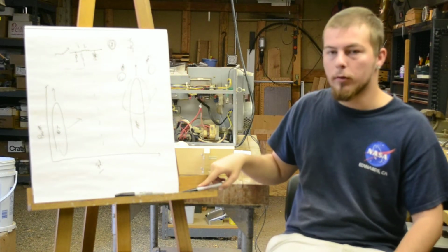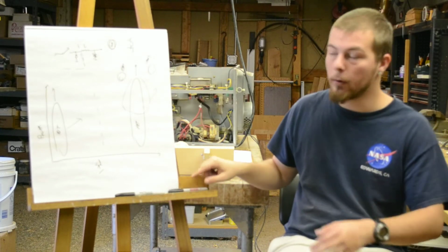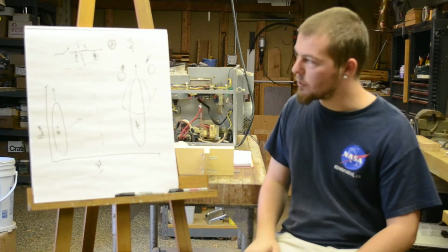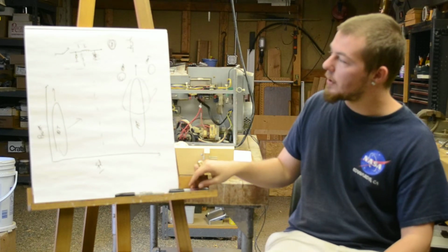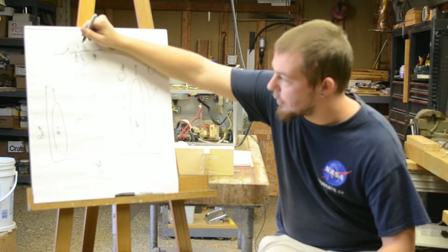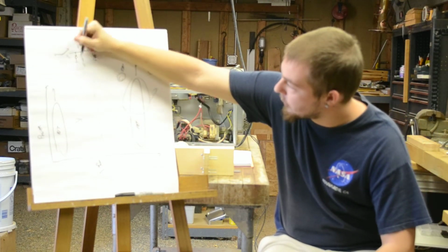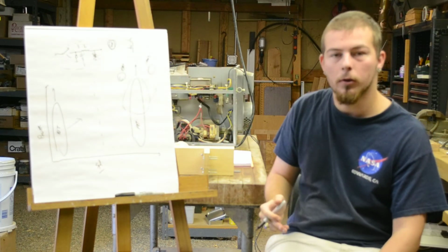Boost controllers and boost circuits are another sort of thing, but I'm not going to spend any time going into that because the boost topology is pretty much a buck topology, except you switch around a few components. You have your inductor where the switch is, your switch where the diode is, and the diode, you essentially go full circle.